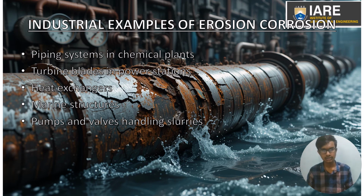And after that, heat exchangers. The continuous turbulent flow of hot fluids inside the tubes of heat exchangers wears down the oxide layer, and it leads to localized corrosion and thinning of metal. And after that, marine structures. In marine structures, the seawater movement and wave action combined with salt and sand particles constantly erode the surfaces and promote corrosion, especially in offshore platforms and ship hulls.